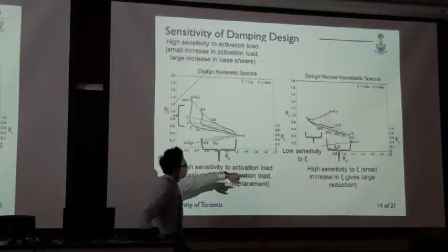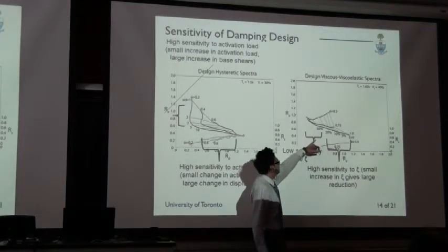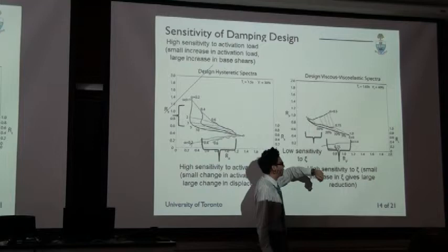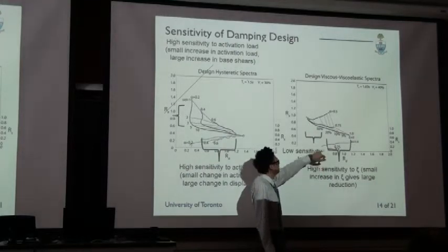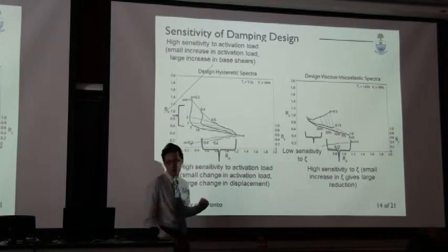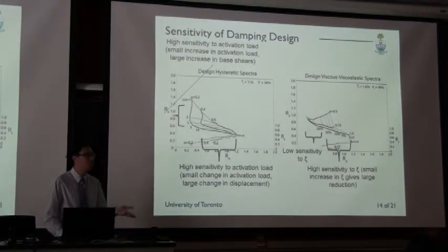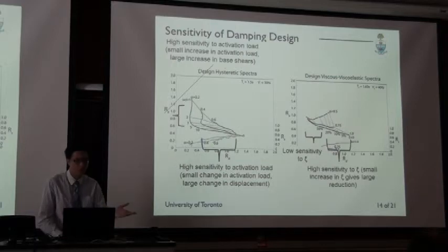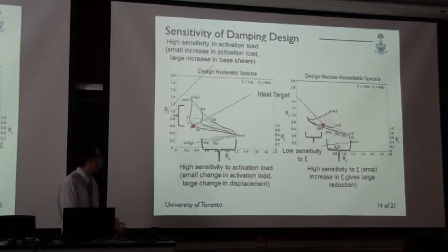Also, note that a slight increase in damper stiffness leads to a large decrease in this residual displacement. So that's something to consider. And this information is immediately obvious in performance spectra. For example, an engineer might select ideal solutions in the proximity of those two points.